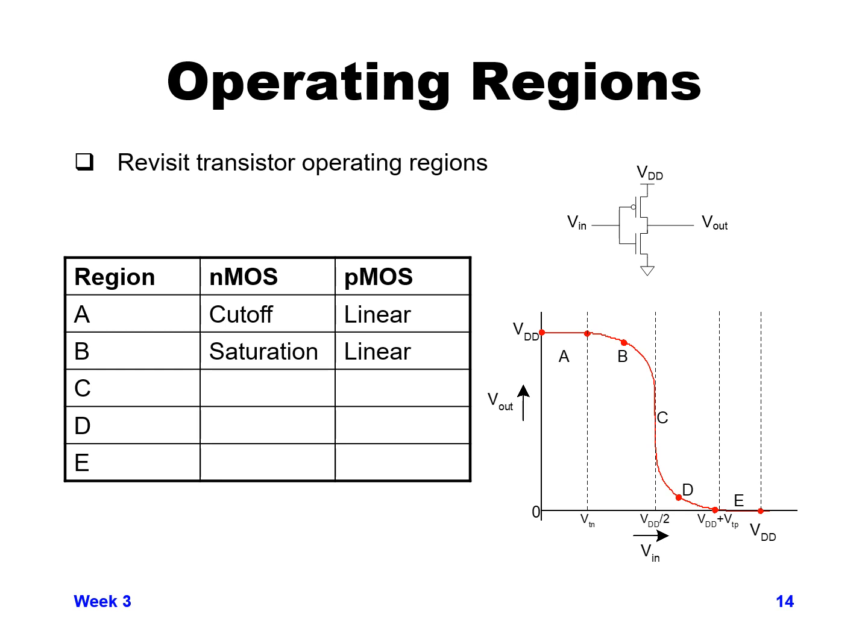And the PMOS device, though, is still in linear region because, since Vin is so much lower than VDD, the PMOS device has its VGS turned on well enough, but the drain to source, since the output voltage is still so close to VDD, it's only in linear region.